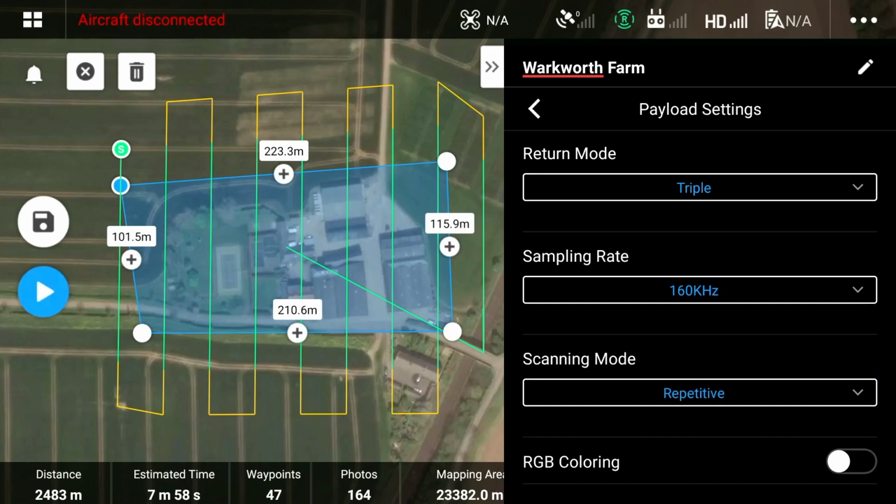Alternatively, a non-repetitive scan type could be selected, meaning that the vertical field is wider, but the accuracy is lower. This mode is recommended for capturing data of complex structures or building facades, and works well with oblique mapping missions.